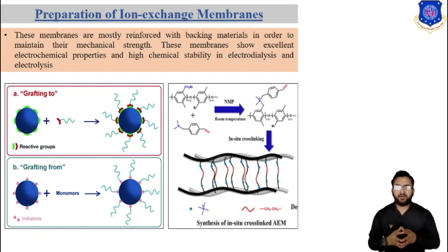An ion exchange membrane can be prepared by grafting of a polymerization monomer onto a polymer film by gamma ray irradiation. The films used are generally polyethylene, PTFE, polypropylene, polysulfone, and polyfluoroalcohol, while acrylic acid is mainly used as a monomer. Trifluoroacrylate and styrene are used in some cases.